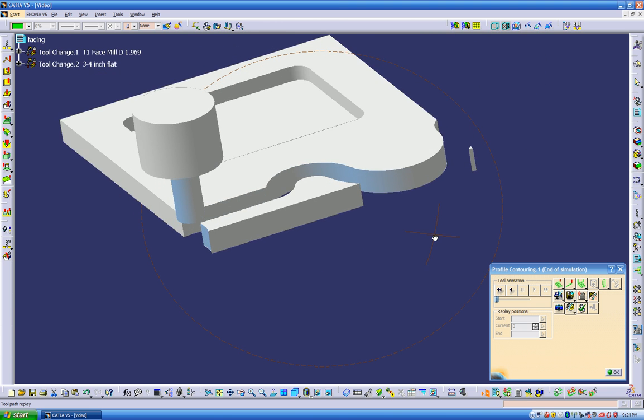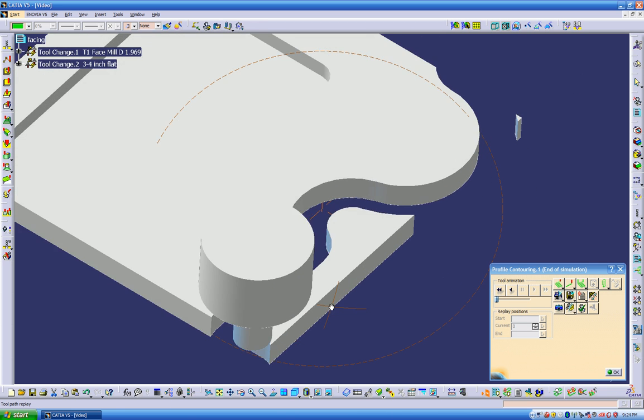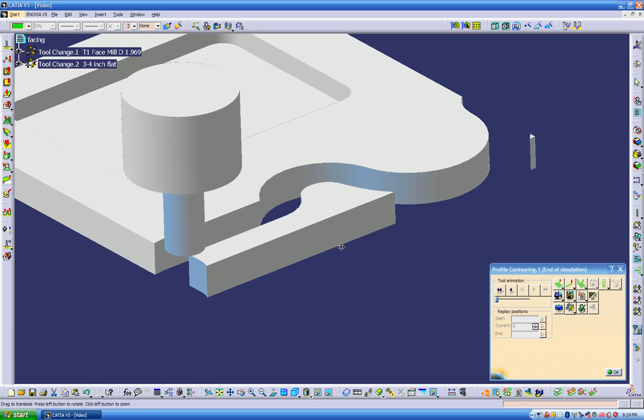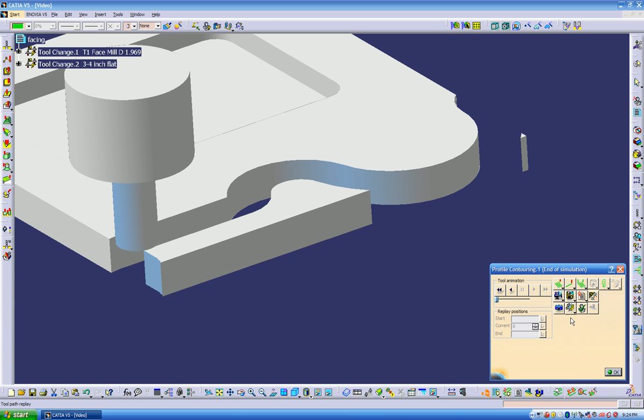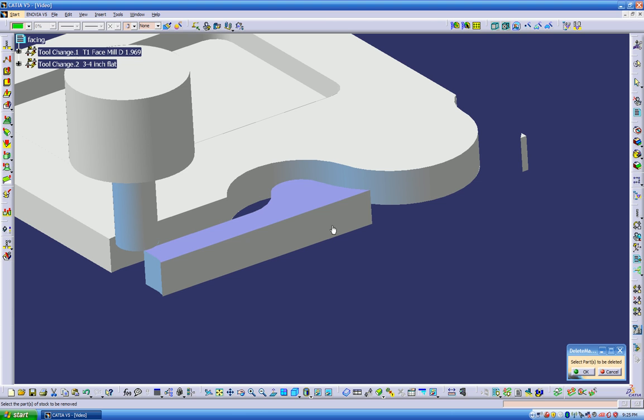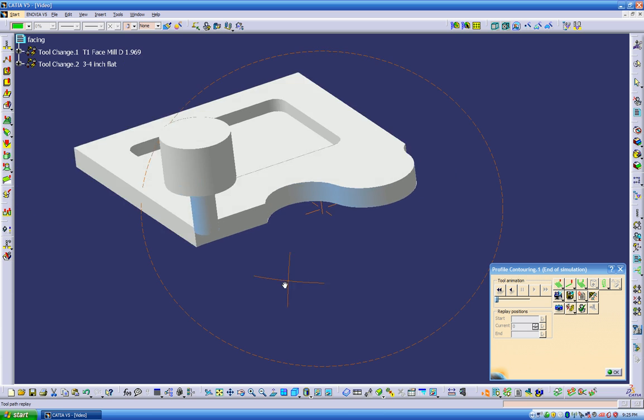that looks beautiful. Now also we can remove these chunks of material over here. Those are called chips or chunks. And if we go in here, it's got one option. It's called remove chunks. So just click on it and it's asking us what we wanted to remove. Click OK and then we remove the chunks.